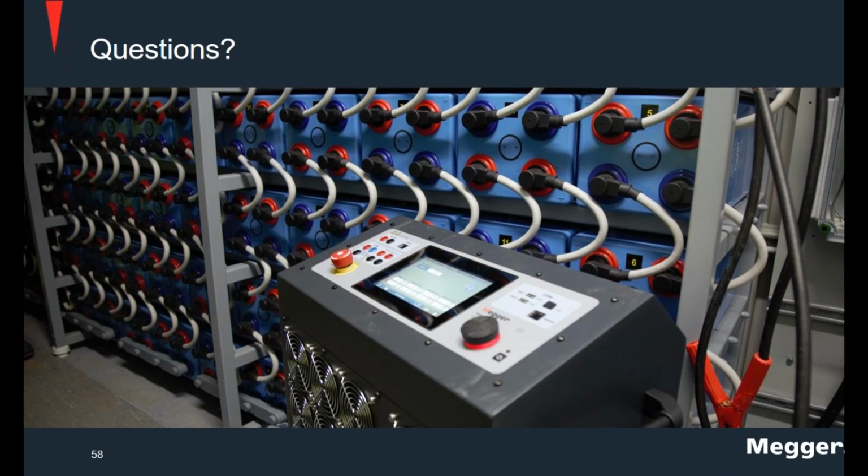Daniel, what's the appropriate float time before a load acceptance test? Hello, guys, and as Kat said, thank you for attending. This one goes hand in hand with that section that Sanket talked about, right? The float current. So again, this current being the result of the float voltage that the charger is applying to keep the battery charged.